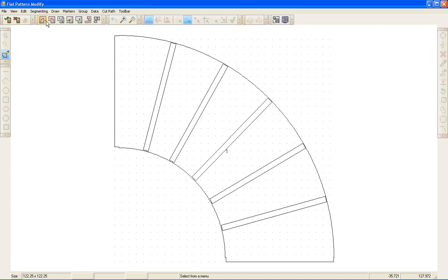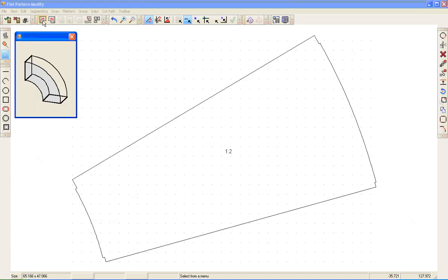Again, you always want to get into a practice of going through and looking at each blank and making sure that the segmenting seam is applied properly. Because when you're talking about a segmented fitting, you're talking about a lot of money that's getting tied up into a fitting. For one thing, because it's so big that it needs to be segmented. But another thing, it's being segmented, so somebody's going to have to put that much more time into it to put all those pieces together. So let's go through. We're going to look at each blank.